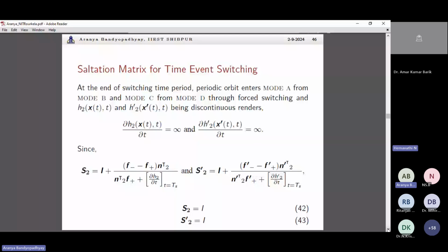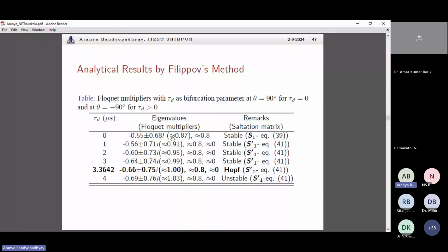And to answer the first question, for the nominal type of parameter values that we have taken into account, we are seeing that at less than the 10% mark of the switching time period, I think for our case it was 25 kilohertz, so 40 microseconds was the switching time period, even at less than the 10% mark, manifestation of instability was occurring, and this was due to the Hopf bifurcation. And the interesting thing is that you can predict it using state space average modeling or Bode plot.